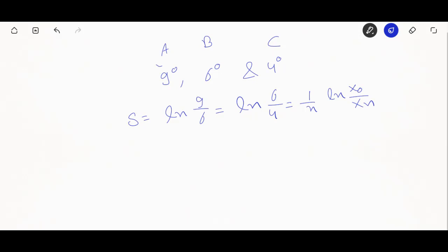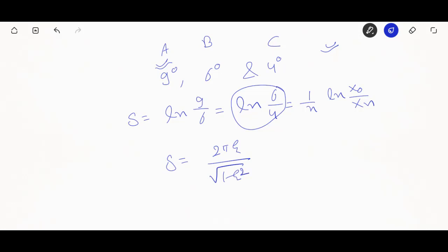In case we have the initial and final amplitude, and we have this logarithmic decrement, we can go through it. Using this logarithmic decrement, we can calculate our damping factor from this equation, right? This damping factor is very crucial for designing any system on the basis of vibrational aspects, right? You can go through multiple formulas to calculate the values.